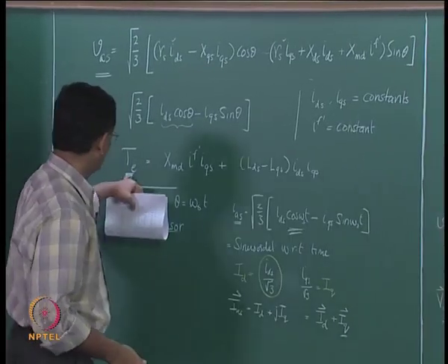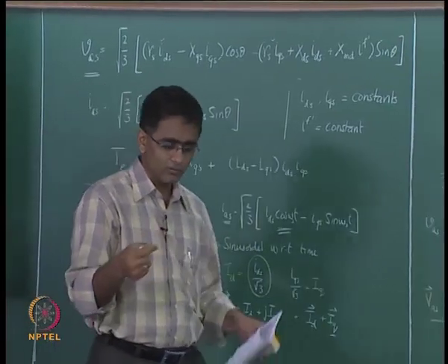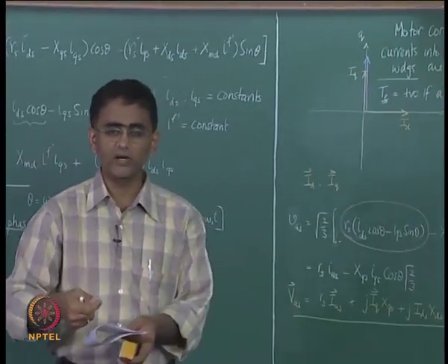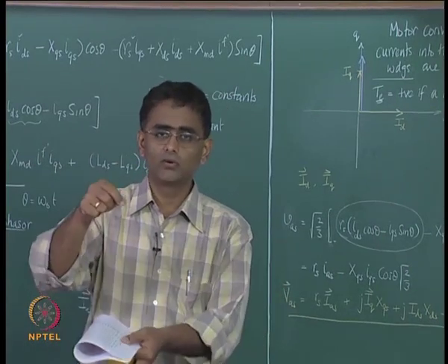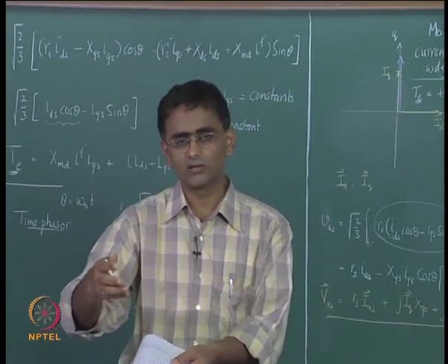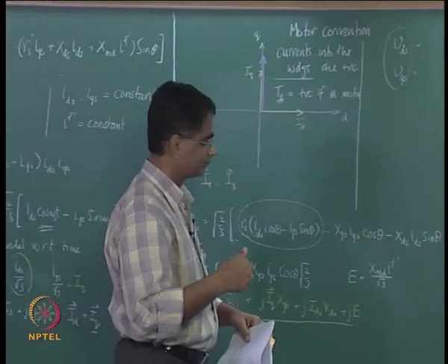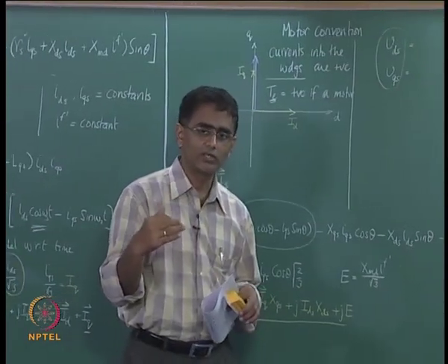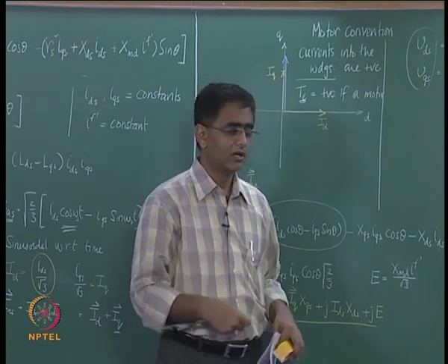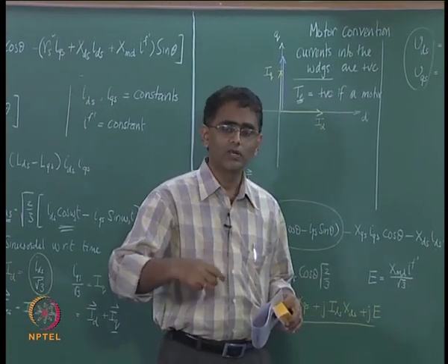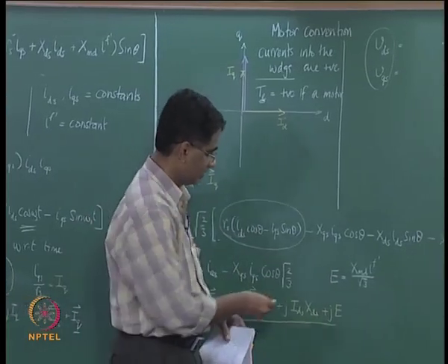But what can be done in the synchronous machine? You know that when you synchronize the machine, you would have adjusted the field excitation so that you get the voltage that you want at the speed that is required. Now from that level of induced EMF, or from that level of field excitation that you have given, after synchronizing one can either increase the field excitation or decrease the field excitation.